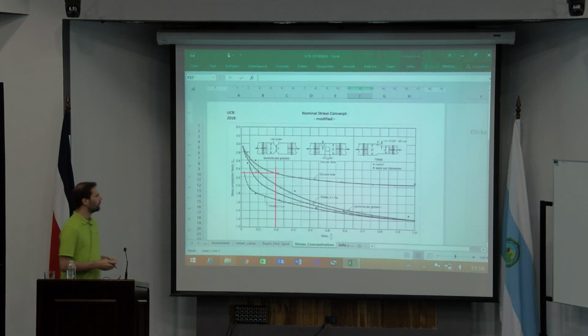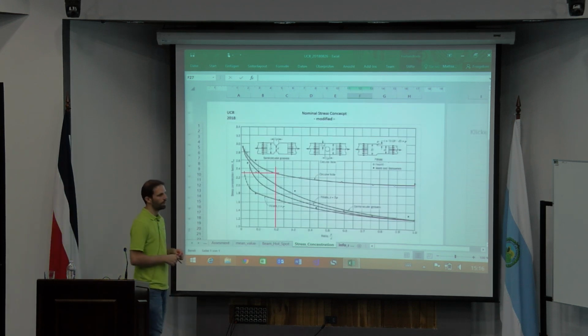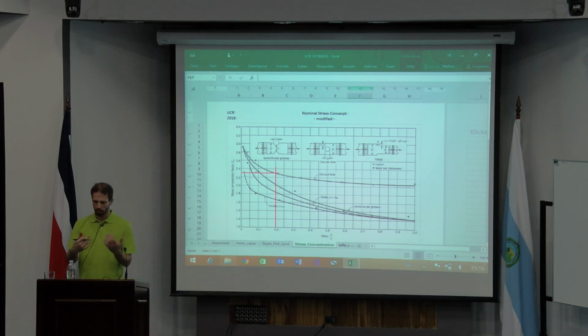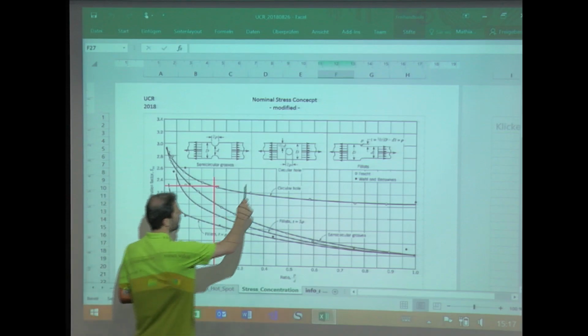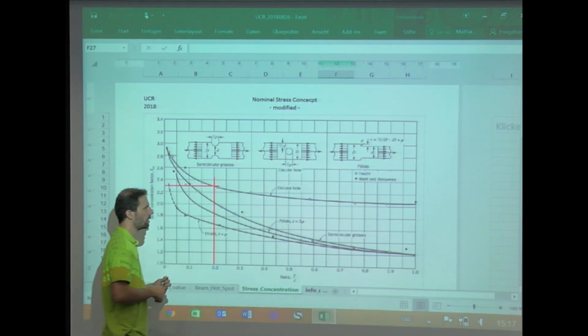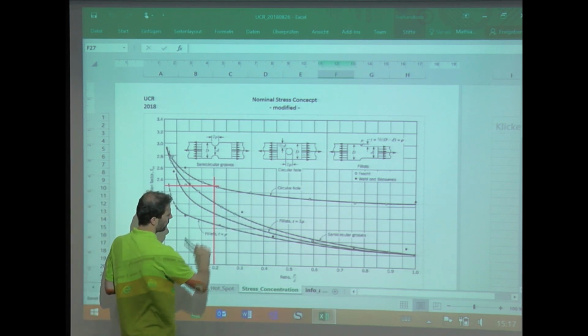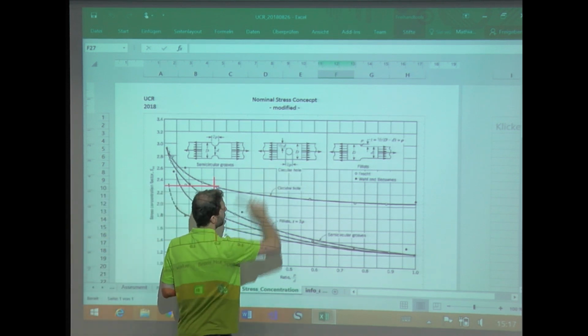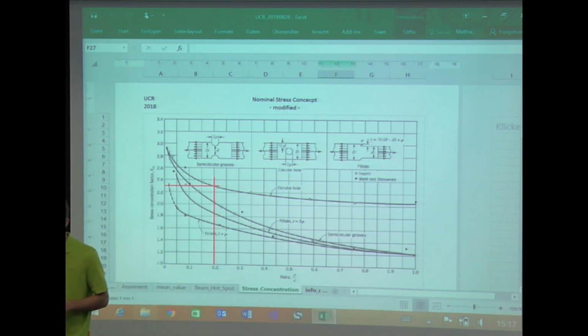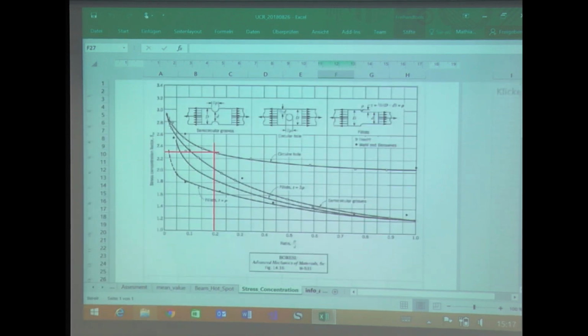And so, for example, you can go and say, okay, at this side you have, for example, the plate with the hole and the fixed boundary situation. So at this side we have a fixed boundary situation, and in these tables usually you also have applied a Poisson ratio of 0.3, and due to this, with the geometry, you can calculate in the linear elastic calculations some drawings like this.